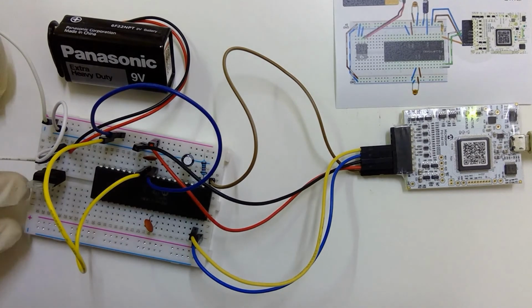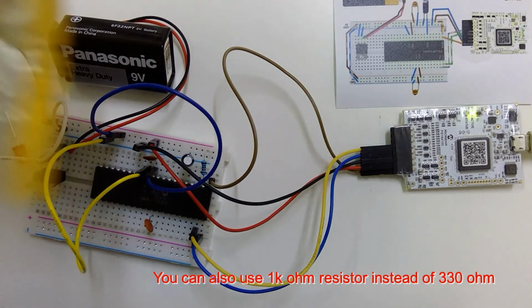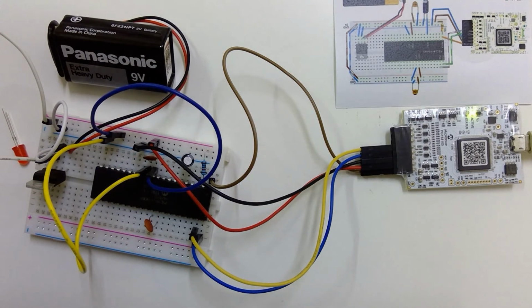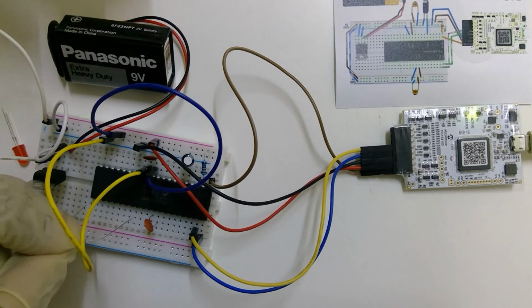So let's start with a resistor. In the packet you will find 330 ohm resistors. You use one of these resistors here on one of these 4 pins, pin number RD4, 5, 6 or 7, which is pin number 27, 28, 29 or 30. So I will use one of these pins here.